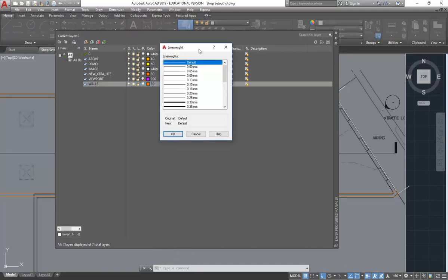Have you looked much at line weight yet? When you've been drawing even? Yeah, see about light, medium and heavy lines. And so what have you been using for your heavy lines? Oh, 0.8, wow, that's heavy. Gee. Yeah, no, that's okay. I normally only go to about 0.6 for heavy, or even 0.5. But, yep, that's okay. If you're doing it by hand, they are sometimes pretty heavy. So that's okay. But with computer drawings, you generally would use lighter line weights than that.